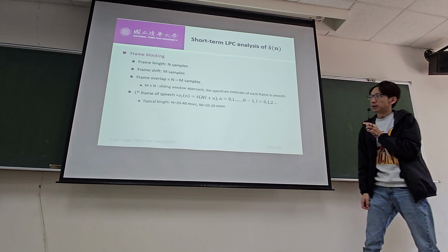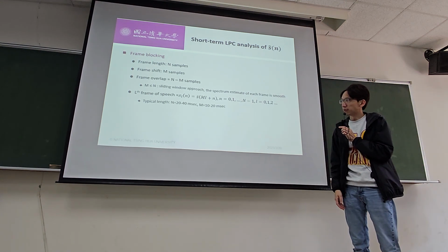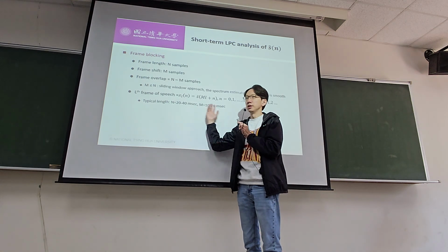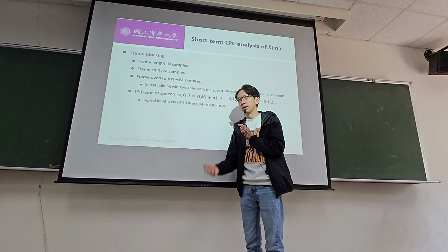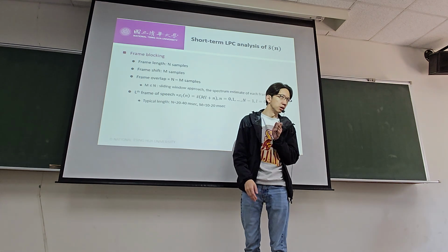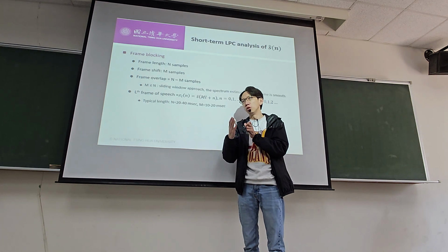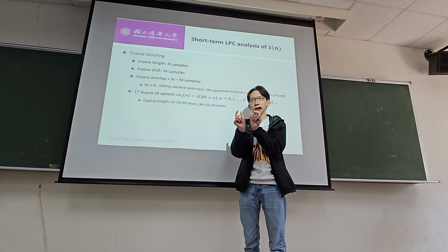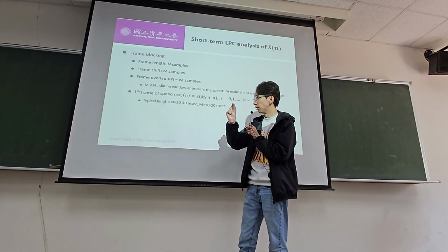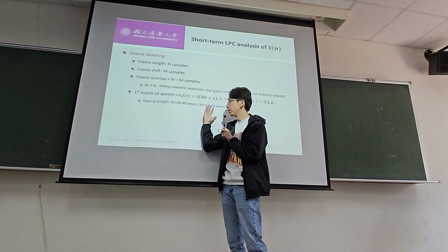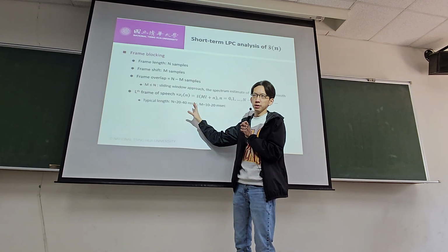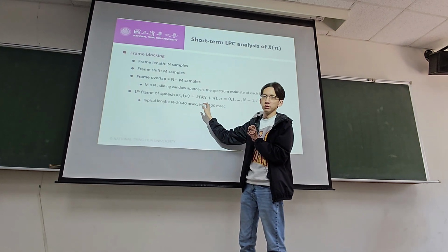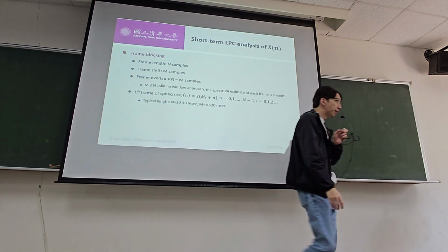The typical length of the window we choose is between 20 to 40 milliseconds with shift about 10 to 20 milliseconds. So this is empirical. Usually that comes from experience, and also because we know a little bit of narrowband and wideband analysis. This window length choice decides how wide your main lobe width is. This is the proper choice. For me, I usually see things like 40 millisecond window and 20 millisecond overlap. If you want to make it smaller, that's okay too. So 20 to 10 millisecond overlap.